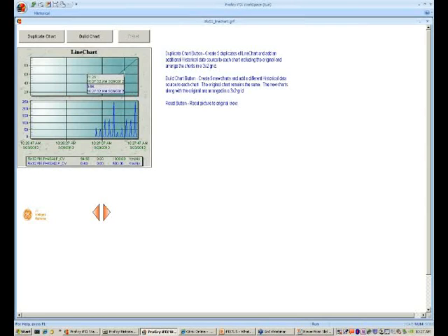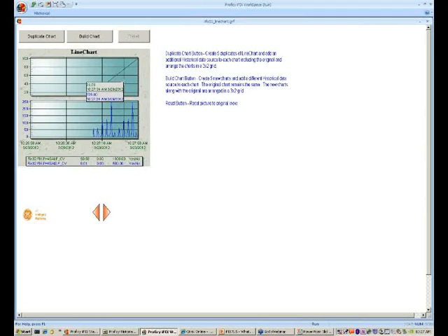But at least it declutters your trend object if the operator wants to study it in more detail and doesn't want all pens confusing the information that he's seeing. So that's one ability that the new chart object now supports.